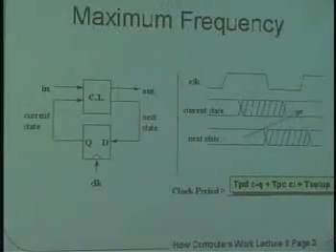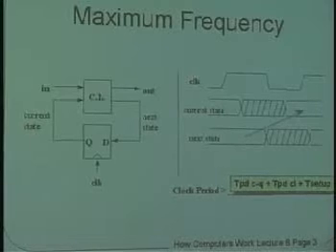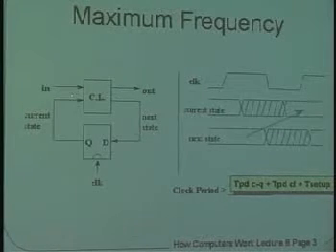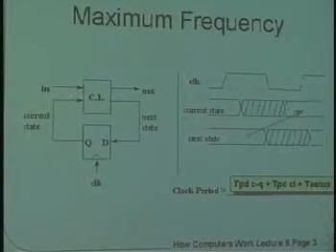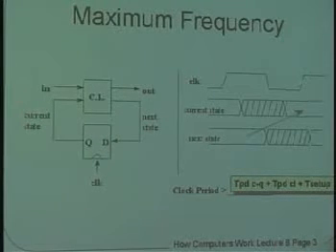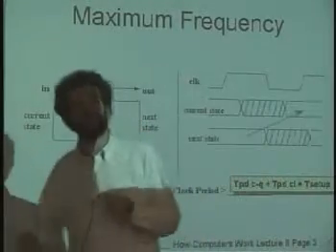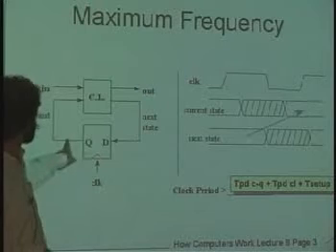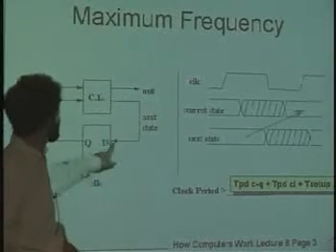Okay. The second constraint that we had with regard to timing was when we could click the shutter the next time, which is a question of when does the new data about the next state come around through the combinational logic in order to get back to D. And if you remember, there we were talking about the propagation delays, or what's sometimes called the maximum propagation times, between the clock and the Q. And after that time has passed, there's some propagation time from here to here, then back around.